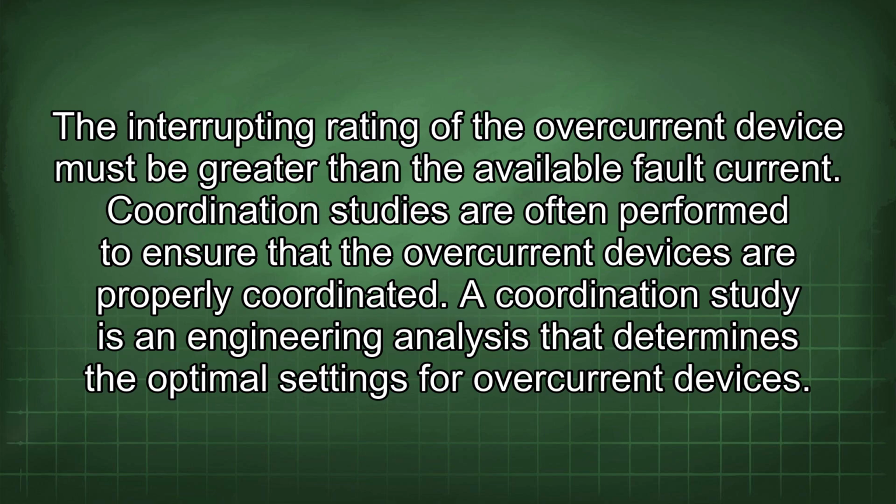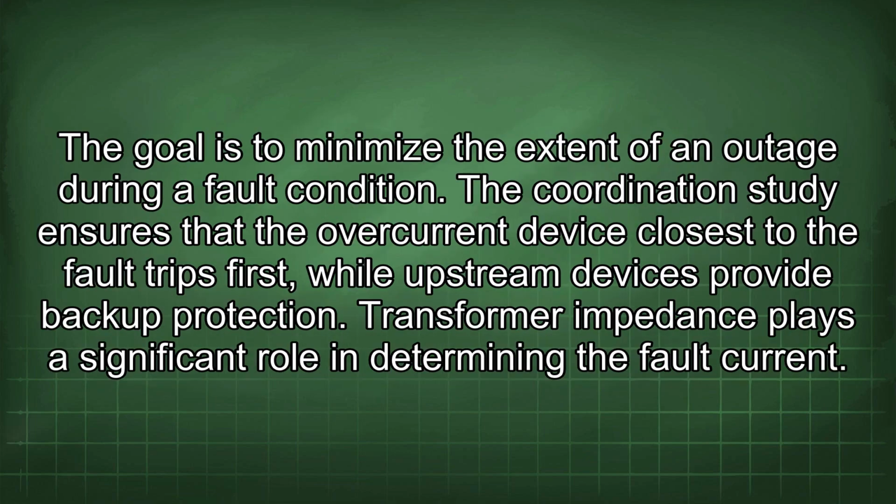Coordination studies are often performed to ensure that the overcurrent devices are properly coordinated. A coordination study is an engineering analysis that determines the optimal settings for overcurrent devices. The goal is to minimize the extent of an outage during a fault condition. The coordination study ensures that the overcurrent device closest to the fault trips first, while upstream devices provide backup protection.